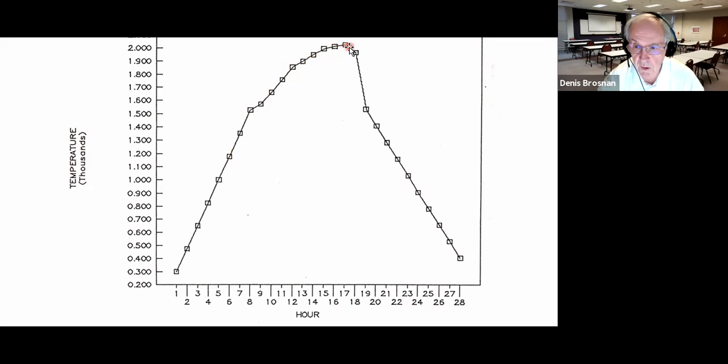in the kiln. Now in the past, maybe a generation ago, we cooled off more slowly, okay? And you're going to see that that just requires a lot more time, meaning a longer kiln. But with modern technology, brickmakers learn to apply the quick cool. So they cool very rapidly to a point at which the glass begins to solidify.